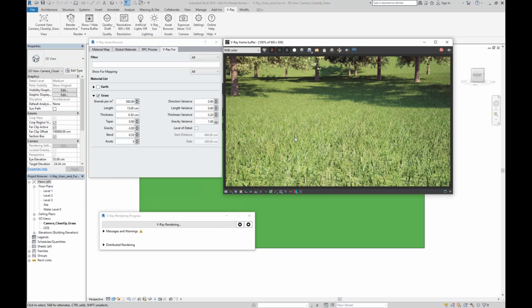Very fast, I will try to go over the parameters because as I already explained, I have a huge area here and I have assigned grass to the entire area, which is not good and you have to avoid it. Grass is to add detail to your images, so it is better to assign it to a small portion of the image, the one that will be closer to the camera and the one that the camera will see detail in, because here in the background, I don't need such detail.